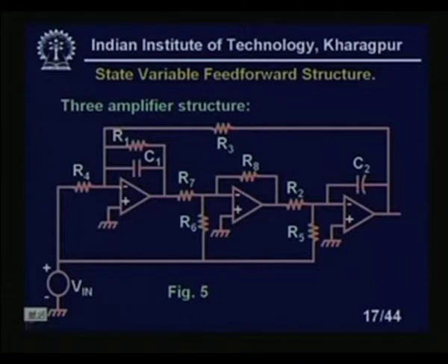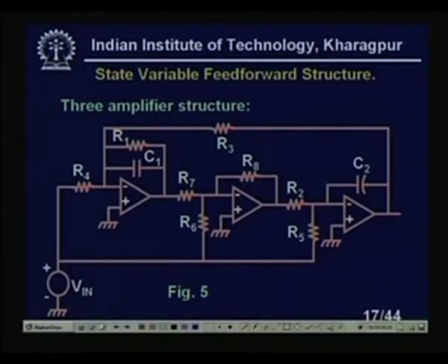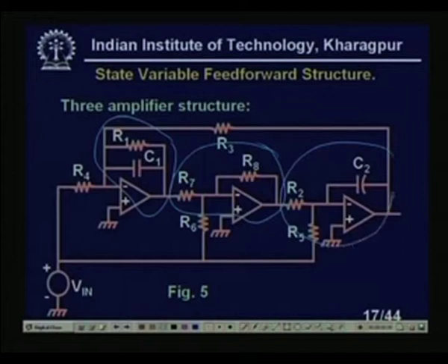You see that we need 3 amplifiers. Why is it called feed forward? You see there is a feedback, no doubt, in the state variable structure. I have a lossy integrator. So this is a lossy integrator, right? This is an inverter, a simple inverter, and this is another integrator, is it not? So, the first one is the lossy integrator or damped integrator, then you have an inverter, then we have again